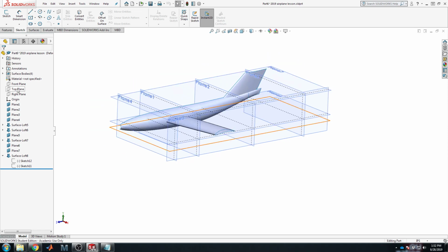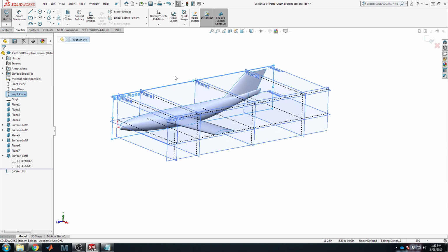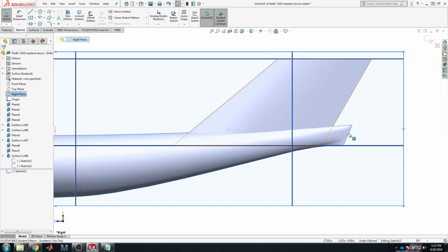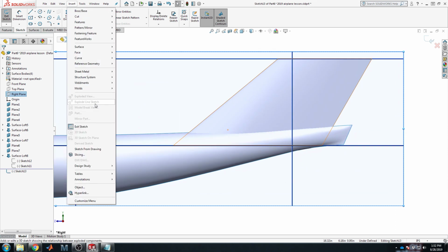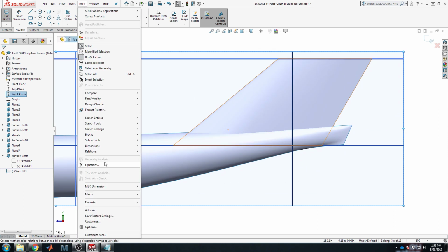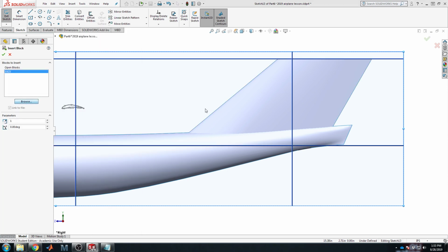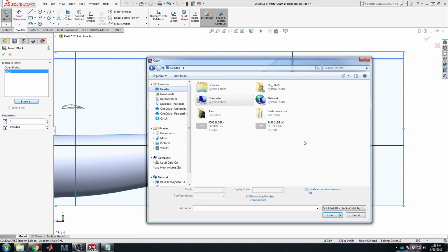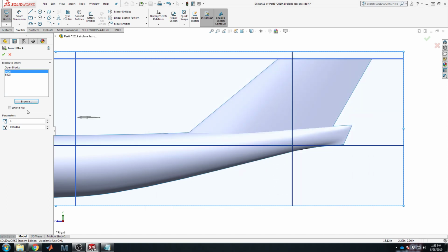So now to make the horizontal tail, let's go onto the right hand plane, new sketch, go here to the back, and we can insert, well, I guess it's under tools. I think it'd be insert a block, but okay, whatever. Blocks, insert, browse for the new file. Should be on the desktop, 0006. 1 inch long. In fact, instead of that, let's have the root of the airfoil be 7 inches, 0 degrees. Actually, some negative incidence is typical for horizontal tails. So let's do like -3.